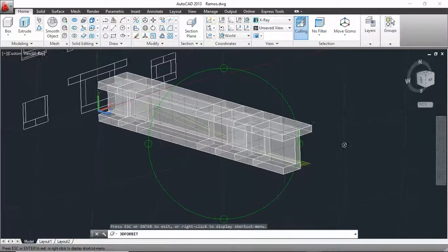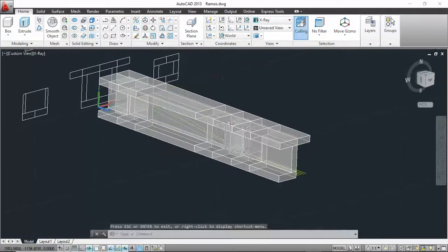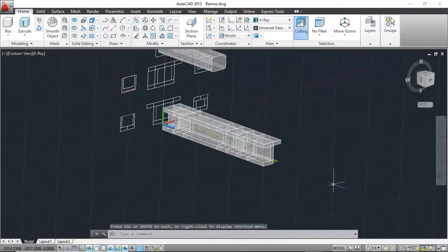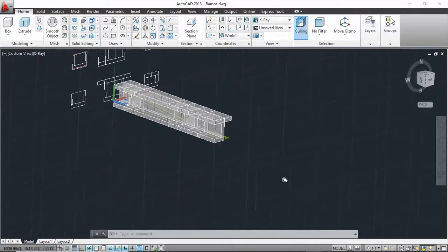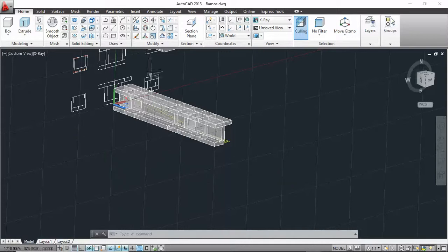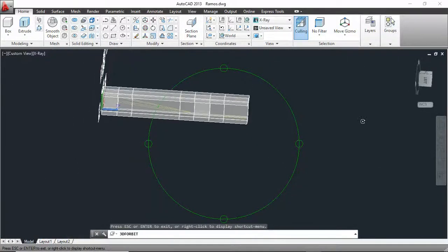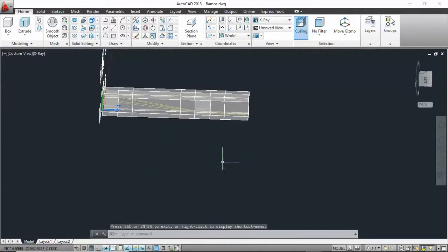Another thing is that I cut my volume and it's not a full beam. I cut from the middle of the stem and along the symmetric axis. It makes my model smaller, and also my output file is smaller, and it eases the convergence and increases the solution speed. I strongly recommend you to use the symmetric specification in your modeling if it is possible, and for example your model and your loading both should be symmetric to use these kinds of tricks in your structure.